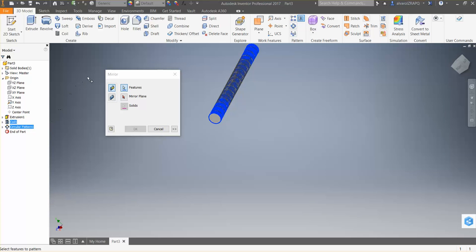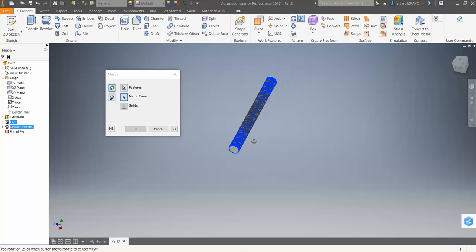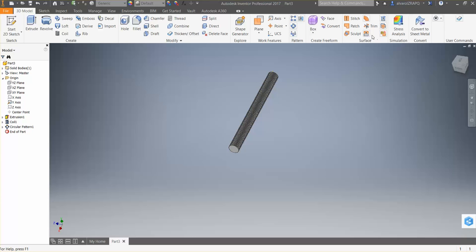Sometimes, okay, and the plane about which you want to mirror this is the YZ plane. So it'd be this one. But wait a minute, you see the YZ plane is on that face. Whenever you want to mirror, you want to have a plane that is cutting the thing in half. This one is not cutting the thing in half. So let me go backwards, and now I need to create a YZ plane. Just shift it to the middle.